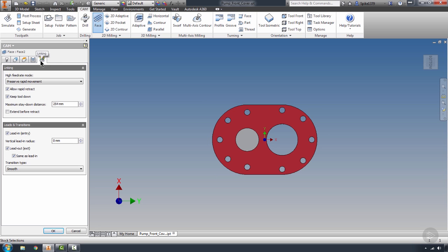Moving on to our final tab, and that's going to be our linking tab. These are, again, passes that are going to be between cuts, between parts, and at the beginning and the end of the feed movement and the retraction movement of the part. Now, how they've broken this down is they have the linking segment and the lead-in, lead-out segment. Now, the linking segment, again, controls how it's going to engage the next cut between selected geometry. In this case, there's only one thing that it's going to be doing.